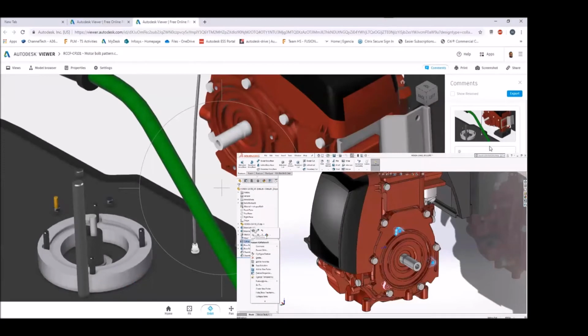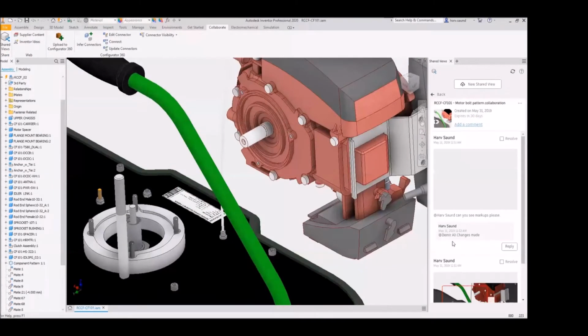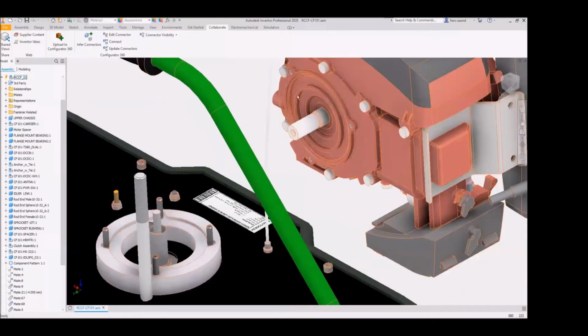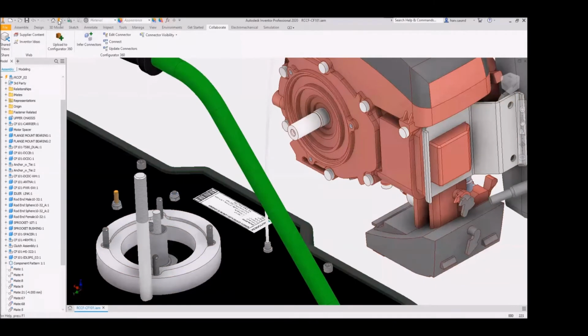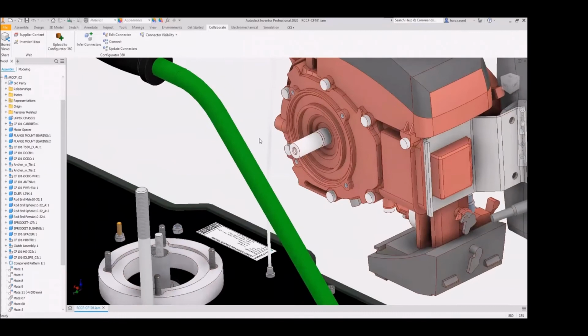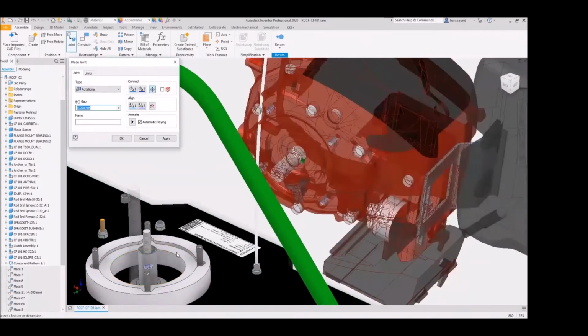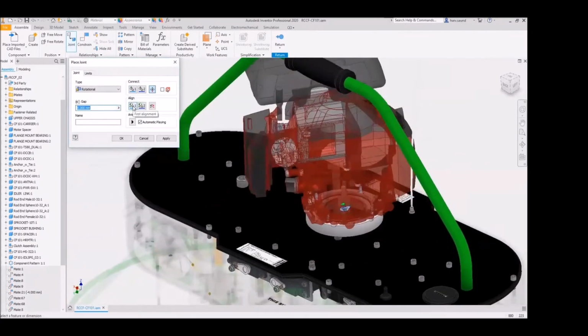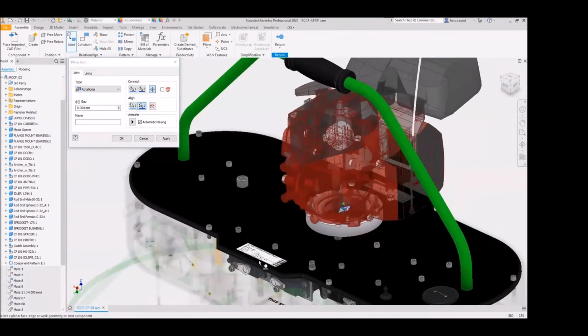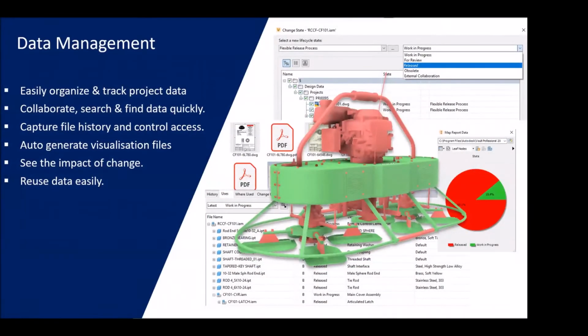So the bottom right there, you can see the SolidWorks going. They're going to go and change from 3 to 4 bolt holes. Once they've finished their design, they're going to hit save, and their model's going to be saved. So now inside of Inventor, all we need to do is an update. So we click update, and their model comes through, and we can now reference those changes. And we're then able to do normal modeling, things like mates, etc., and those will go in. And Inventor will remember our mates and any changes that we've made based on that geometry that we've used AnyCAD for.